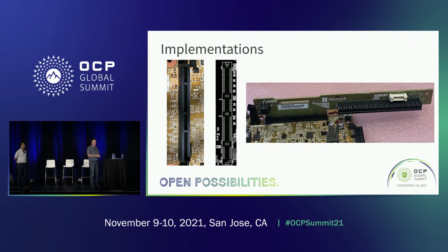Step one: if you're going to be modular, you want something to be able to do A, B, and C, and D. You have to have an ecosystem from which it can do that. That starts for us with a connector. You're going to hear Nilesh Dattani and some other people talk about DC-XPI a little bit later today. Basically, what you see here is a replacement. Prior motherboards all had PCIe connectors. PCIe connectors are great for sticking PCIe PCBs in.